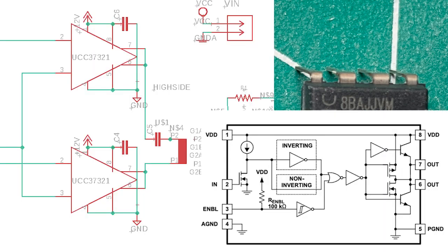High current gate driver devices are required in switching power applications such as this for a variety of reasons. To enable fast switching of the MOSFETs at a specific frequency, namely the resonant frequency, these gate drivers take in a square wave, process it, and output around 18 volts at up to 9 amps for periods of up to 100 nanoseconds. The 37321 is inverted on the input stage, while the 37322 is not. Thus, the chips' output signals are 180 degrees out of phase from one another while using the same input signal.